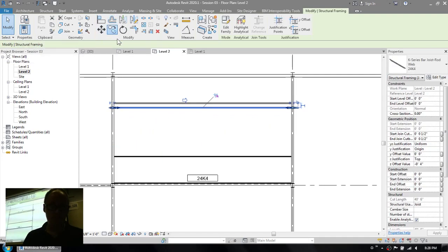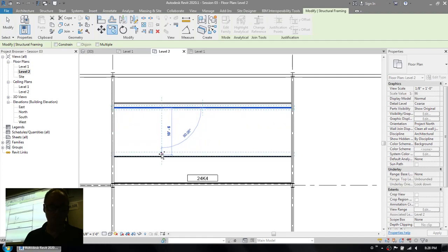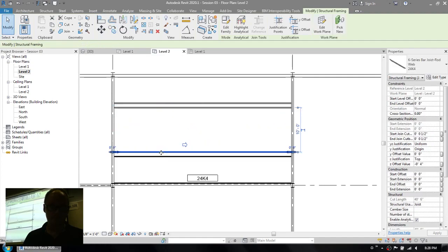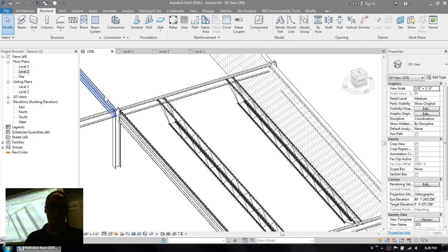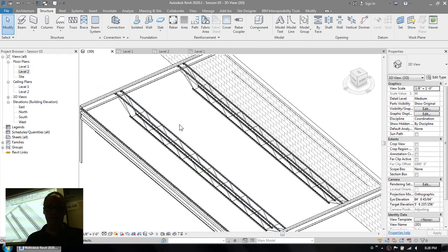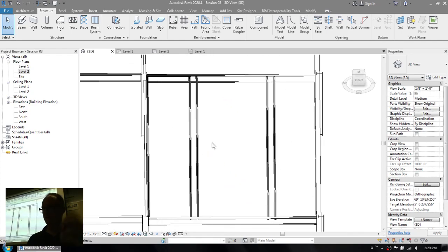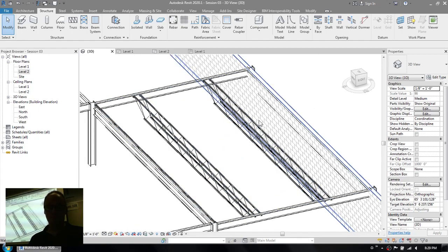And then I'm going to copy it. So I've doubled up my joists on either side because what I'm intending to do here is to run a steel channel the other direction. I'm going to build an opening, right? So you've got your header joists on either side of the opening, and then you draw the structure that's going to go in the other direction for an opening here, say an elevator or a shaft or something of those lines.